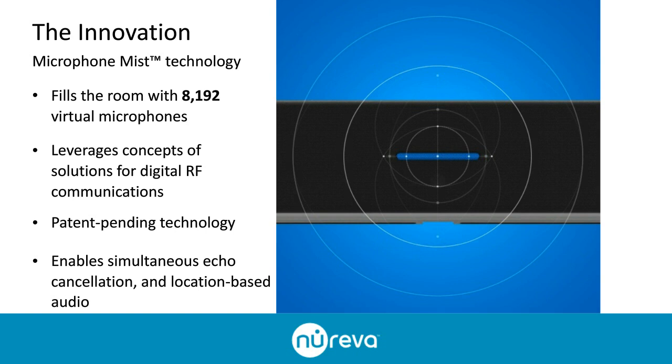And the microphone that is closest to you will be the microphone that will essentially enable. And so we were trying to get the virtual microphone within 1 centimeter of where you're actually speaking. So we're very, very precise about where you are in the room and have the ability to determine that's the amplification we want to do. That's where you want to do acoustic echo cancellation. We want to cancel out perhaps the other sounds in the room, not totally, because we still want people to have a great natural experience, but at the same time we're able to enhance the audio that's coming from that particular XY location in the room.